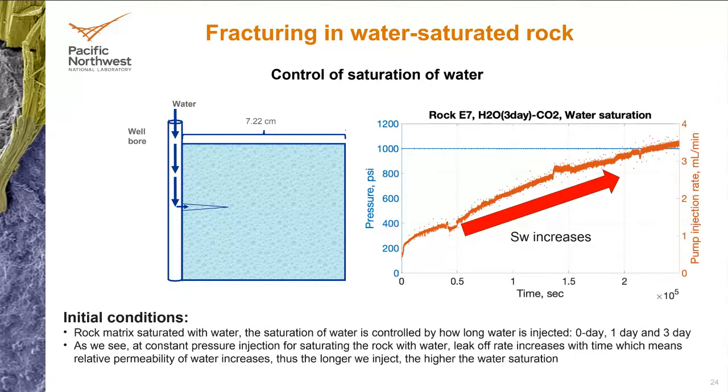Yeah. So what I was saying is, if you dump this rock in a bucket of water at room pressure, it would probably take a long time, months, for this rock to become fully saturated. And I'm not saying injecting for 3 days at 1,000 psi will saturate completely the rock, but definitely we can see that there is a very high flow rate after 1 or 2 days associated to basically the transport of water into the formation. So even though granite is 2% porous, it's pretty permeable.